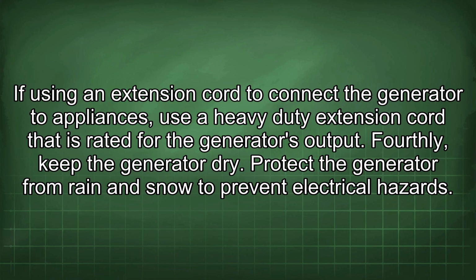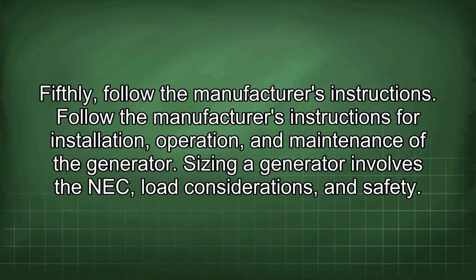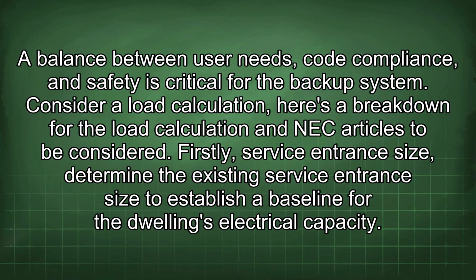the generator's output. Fourthly, keep the generator dry. Protect the generator from rain and snow to prevent electrical hazards. Fifthly, follow the manufacturer's instructions. Follow the manufacturer's instructions for installation, operation, and maintenance of the generator. Sizing a generator involves the NEC load considerations and safety. A balance between user needs, code compliance, and safety is critical for the backup system.